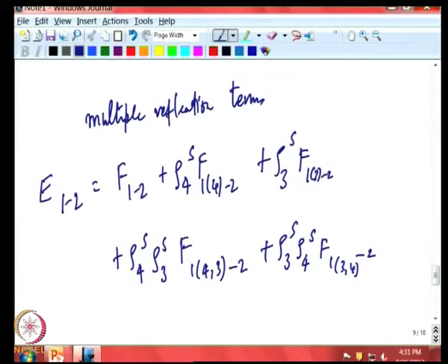And remember, once the ray reaches 2, that is the end of ray tracing, because surface 2 is a diffuse emitter. So, once it has reached surface 2, the story is over, because there is no further ray to trace, because 2 is a diffuse reflector. So, the memory is lost and we do not really have to keep track of any images in 2, because 2 is anyway a diffuse reflector.